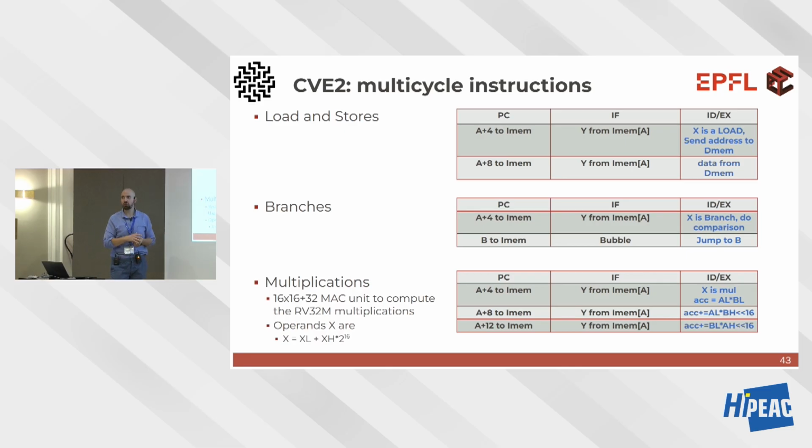While multiplication, again, is done in this case in 3 cycles. There's also a parameter to have it in 32 cycles, so serial. But I've done a bit of profiling, and multiplications are actually there also if you do control applications, to calculate the address of the DMA or doing a few things here and there. So in this case, by doing a few experiments, I chose 3 cycles as the best energy efficient point.